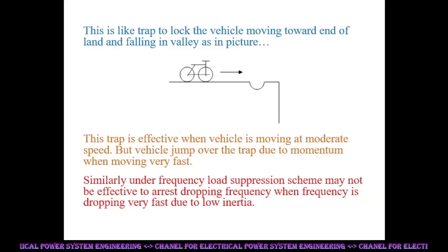Similarly, the under-frequency load shedding scheme may not be effective to arrest dropping frequency when frequency is dropping very fast due to low inertia and or huge loss of generation.